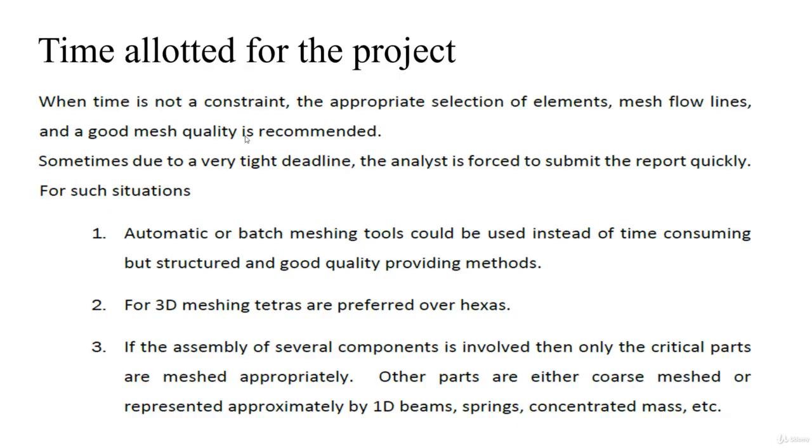Then coming to the final factor, the time allotted for the project. For every project there will be some time. Based on the time, you can use the automatic mesh generation tools, or otherwise you can also do manual meshing by setting up every mesh control, and you can check this mesh. Automatic or batch meshing tools could be used instead of time-consuming but structured, good quality providing methods. Then for 3D meshing, tetras are preferred over hexas.